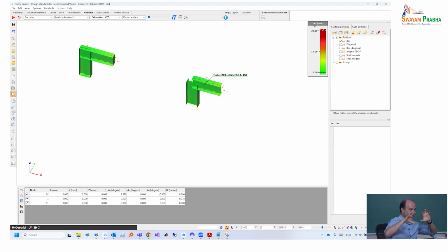automatic hinges. We don't let the beam element transfer the deformation because it cannot. We are releasing it from this exercise, and we are enforcing a certain prescribed behavior to the connected elements because we know what will happen in case of such a box configuration. The beam element doesn't know.